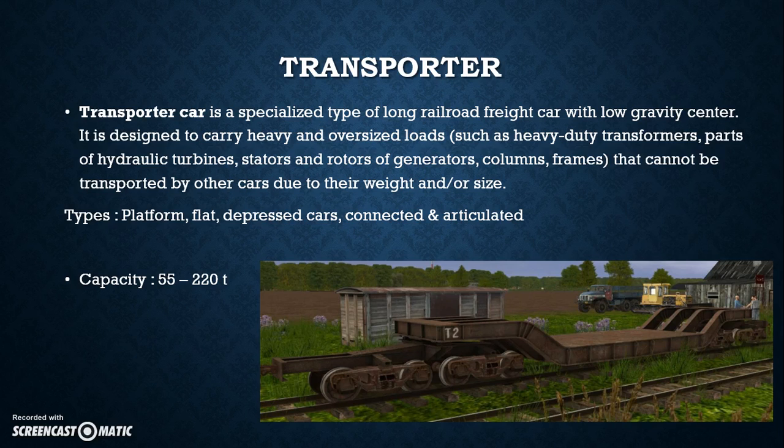The connected transporter cars consist of 2 bearing platforms with arms for supporting and securing long, heavy cargoes, and the middle platforms, serving for the extension of length and the connection of the car parts. Car parts are connected by shortened couplers without absorbing devices. Main types of connecting transporter cars are the 12-axle car, capacity about 120 tons, the 16-axle car, capacity about 240 tons, and the 32-axle car, whose capacity is 480 tons.